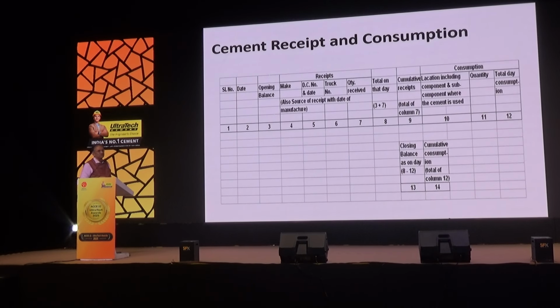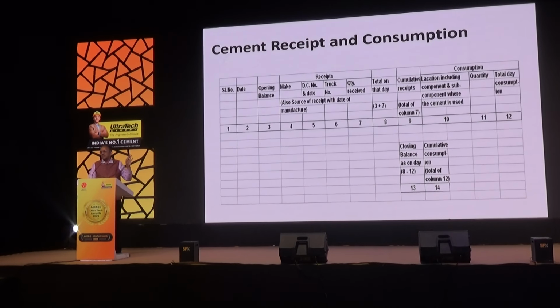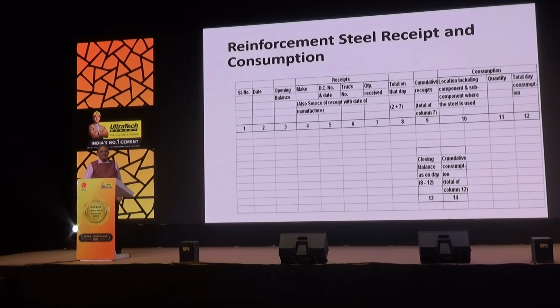If we maintain these formats, then in one of the projects there were cracks in the slab after decentering. I was called to check and confirm what the problem was. Because of these registers, within 10 minutes I could find out what happened at the site, and then we could arrive at the solution. So it saves a lot of time in investigation.